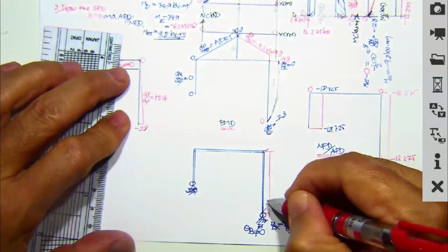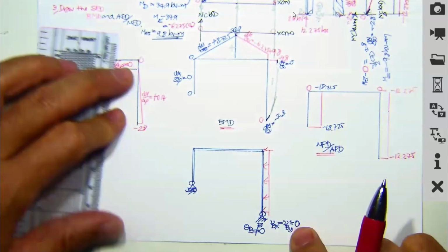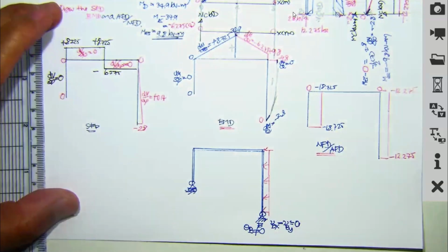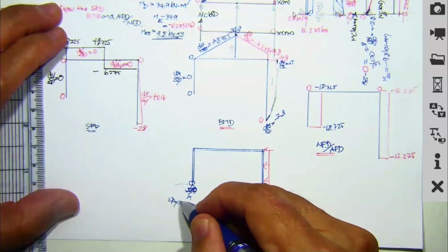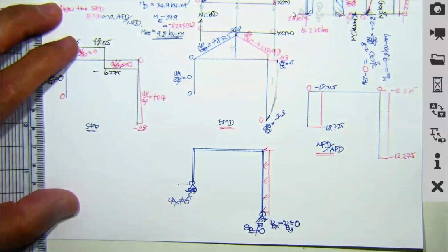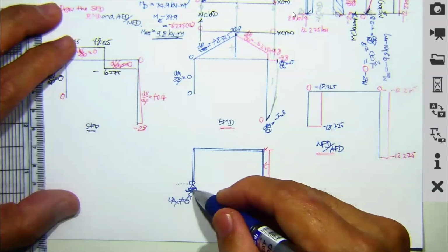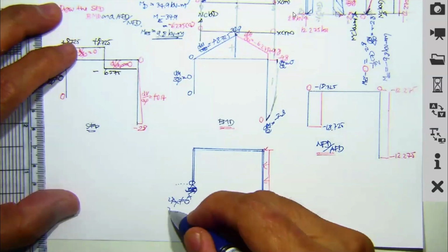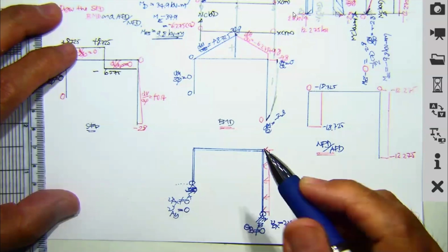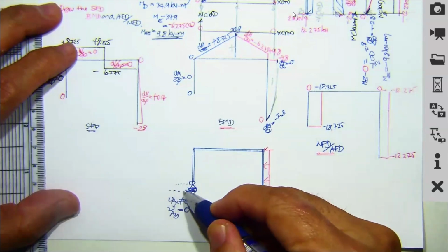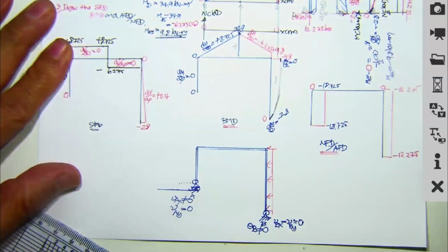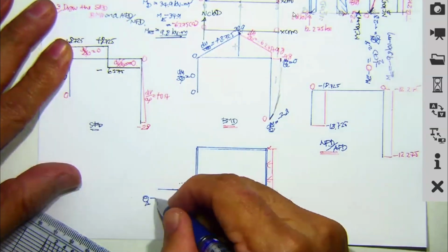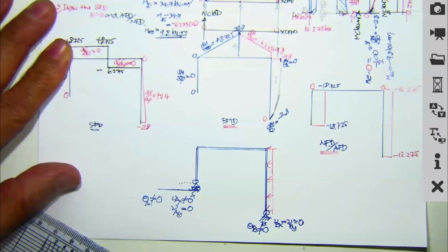One more thing I should mention is the roller at point A. Roller can move in this direction. So V sub AX won't be 0. However, it has reaction A sub Y, so V sub AY is going to be 0. So the movement is supposed to be only in the horizontal direction. How about theta sub A? Theta sub A won't be 0.